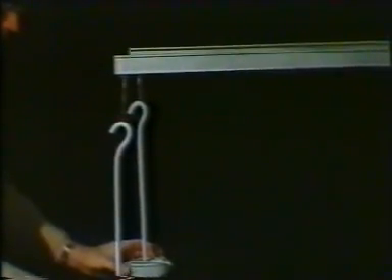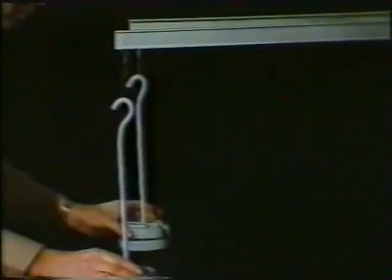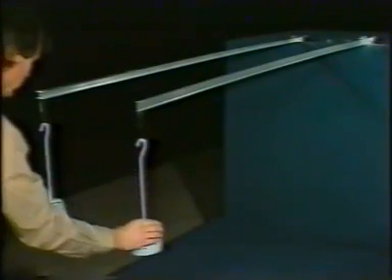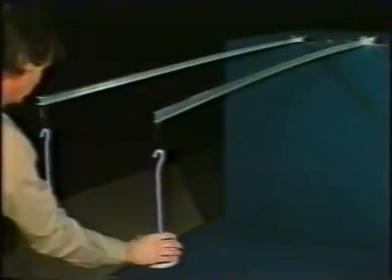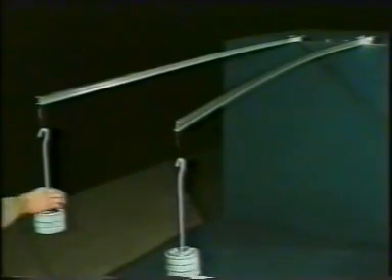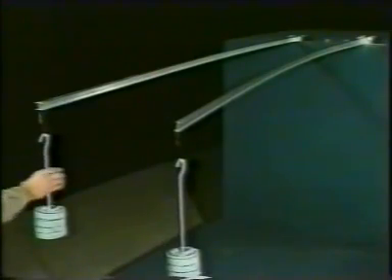Initially, as equal load is applied to each beam, their behaviours are almost identical. However, for the beam with low minor axis stiffness, as loading progresses, instability intervenes. The cantilever on the left does not suffer any instability and would eventually fail by plastic action.